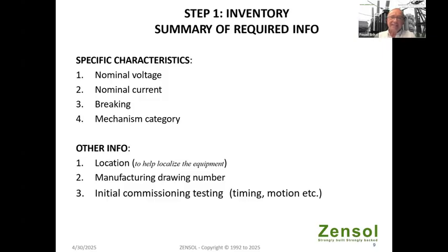In the other presentation on the vibroacoustic on the tap changer, we show this clearly in a slide where you compare offline, you get exactly the same vibroacoustic signature, but when it's online, you can see the arcing at a specific point, and it's easy to recognize.